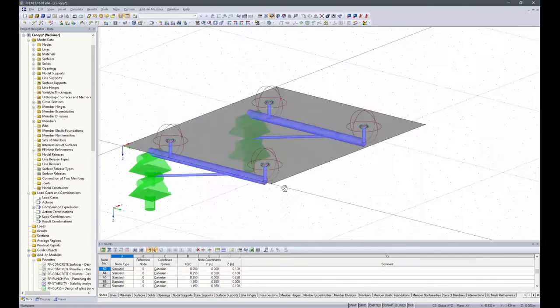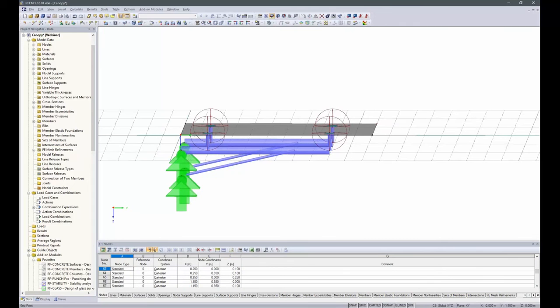So we're pretty much done. Although the construction has to be modeled with an inclination of 5 degrees from the outer wall of the building, which is on this side, because water has to run down, snow has to fall down, so it's not supposed to be straight. We could rotate everything around 1 point, which would be okay, but this would result in other points being shifted sideways, which we don't want.